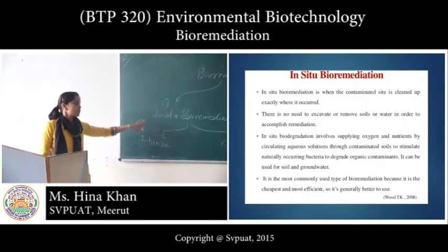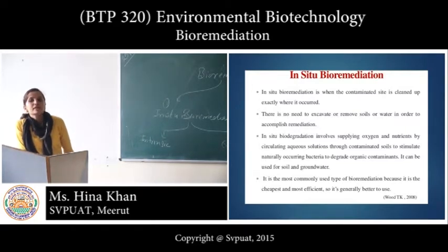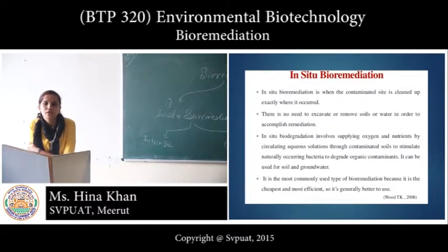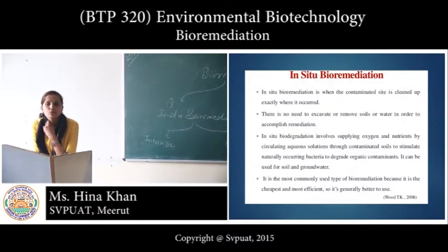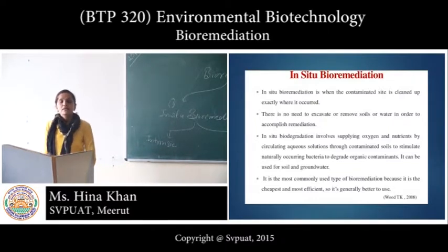Now come to what is in situ bioremediation. In situ bioremediation is when the contamination site is cleaned up exactly where it occurred. There is no need for excavation or removal of the soil or water in order to accomplish remediation. In situ bioremediation involves supply of oxygen and nutrients by circulating aqueous solutions through contaminated soils to stimulate naturally occurring bacteria to degrade organic contaminants.